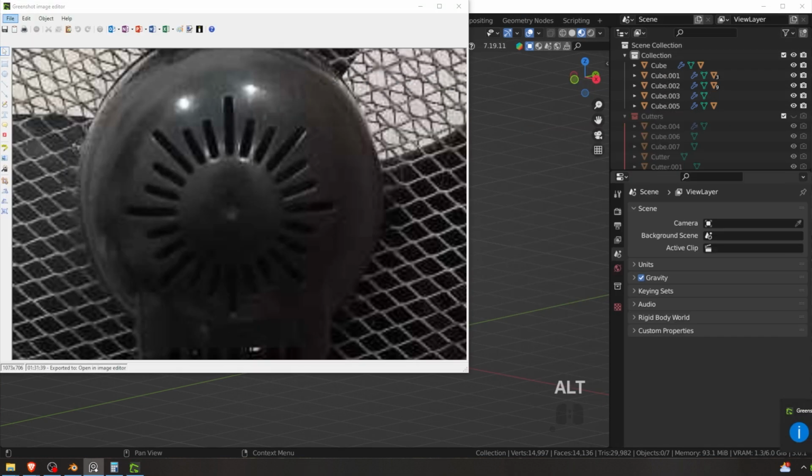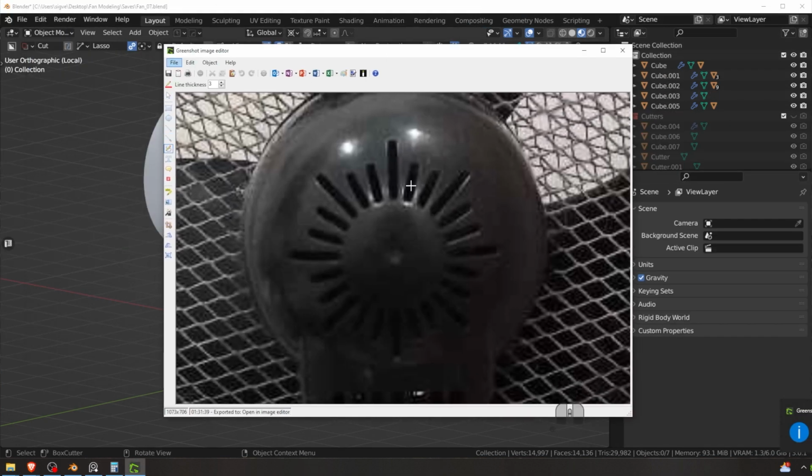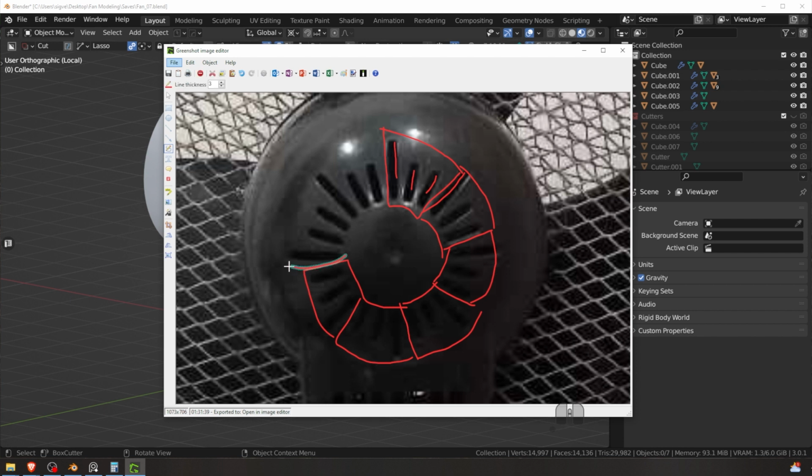So in this case, what we can actually do is just go ahead and create only this section right here. That's all we need. These 3 pillars, that's all we need. It's because it repeats. If you look at it, it repeats the whole pattern. You see? It repeats throughout the whole thing right here. Boom. You see? It just keeps on repeating. So if you're modeling, always look for the smallest amount of geometry that I need in order to create a radial array like that.